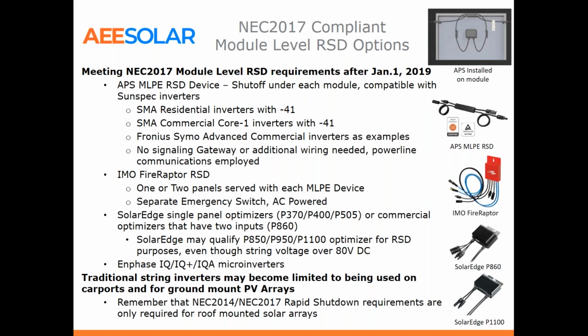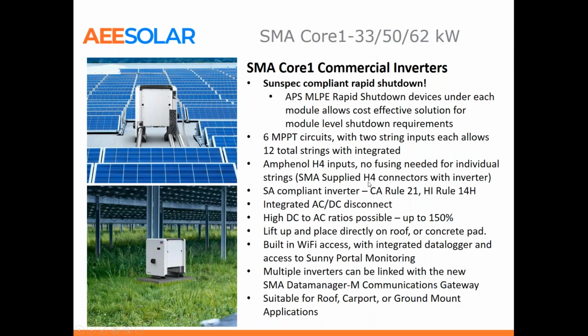and on ground mount arrays, because remember that rapid shutdown requirements are only required for roof mount solar arrays in most situations here. Definitely don't try to put your inverters inside. If you have a nice ground mount, don't put your inverters inside the basement of the building and then get surprised when the jurisdiction having authority wants you to install rapid shutdown on the ground mount. Don't do that.